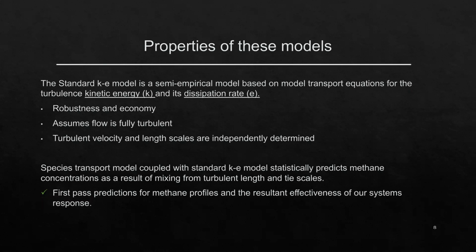So here are a list of a few characteristics of the k-epsilon model. The flow domain at full scale is rather large and can be computationally expensive for a 3D simulation. So its robustness and economy are good features since the mixing and flow itself is rather simple. There is no combustion and other particles being accounted for here yet.